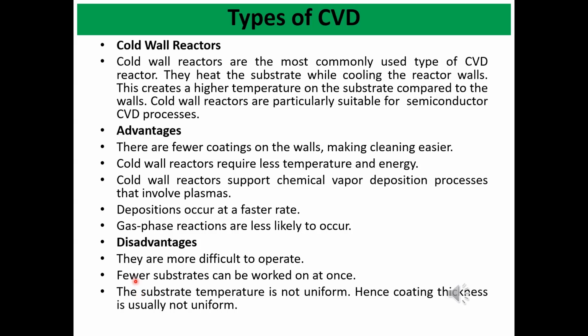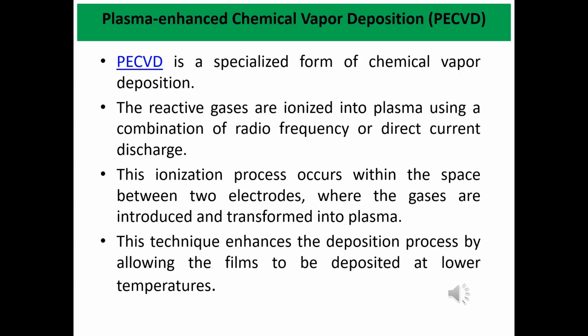CVD reactor, cold wall reactor, that the substrate temperature is not uniform, and when there will be less uniformity of the substrate temperature, then we will not be able to get the coatings or thin films with very uniform thickness.